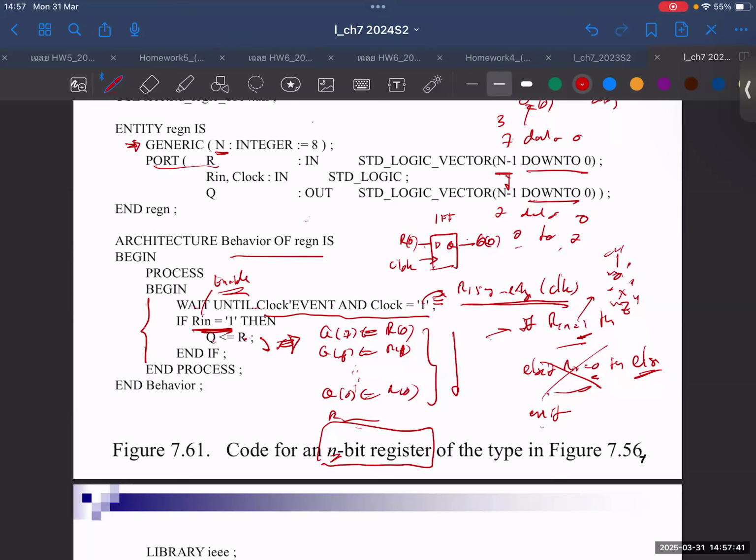You have to understand the language. That's why I'm saying you need to understand it. If you're missing something, you surely get a latch. I used to see this with students. They write this kind of code in software style, with lots of nested if and else, like 10 times.